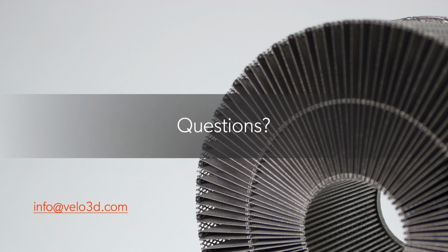Cool. One more question here. Do we have the capability to print multi-material with VELO3D? No, not in the same build. Because it is a powder bed process, you'd have to have some way of blending your powders nicely in the build. That's not something that's made its way to laser powder bed fusion yet.